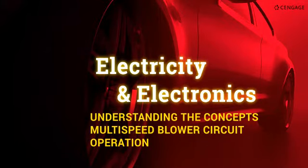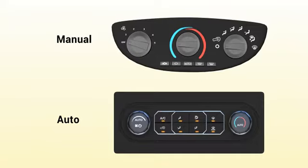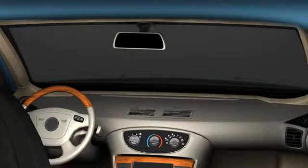Understanding the concepts, multi-speed blower circuit operation. The blower circuit for the air conditioning system provides the airflow to circulate the conditioned air to the passenger compartment of the vehicle. There are two types of blower circuits, multi-speed and pulse width modulation. The multi-speed blower circuit consists of several components.